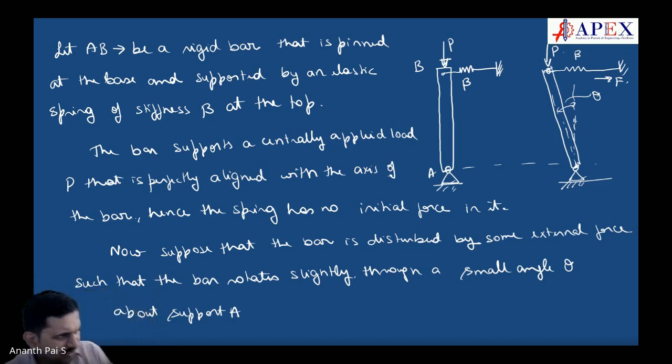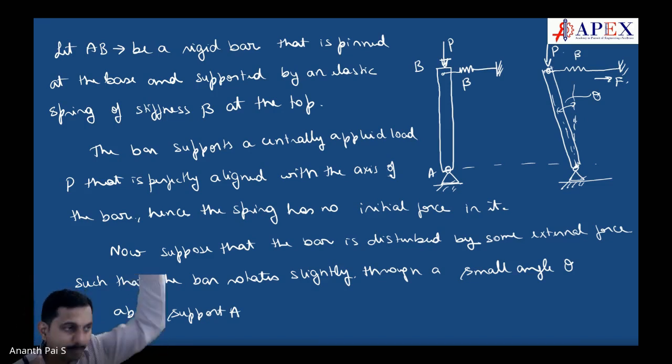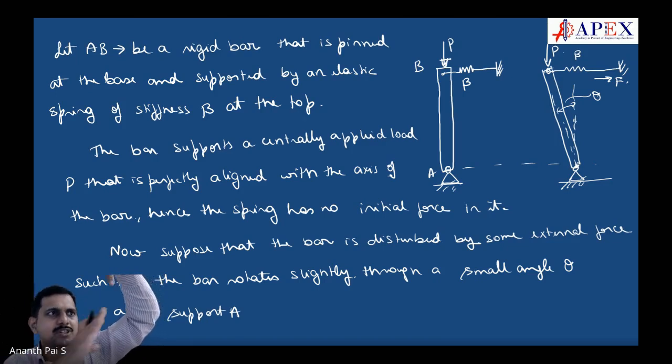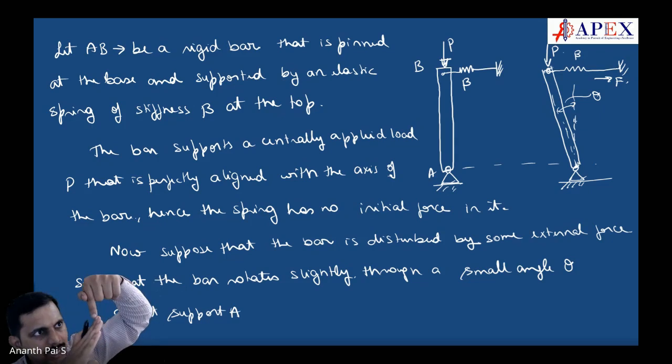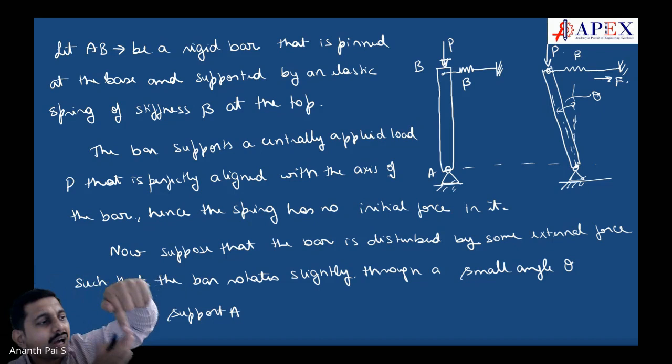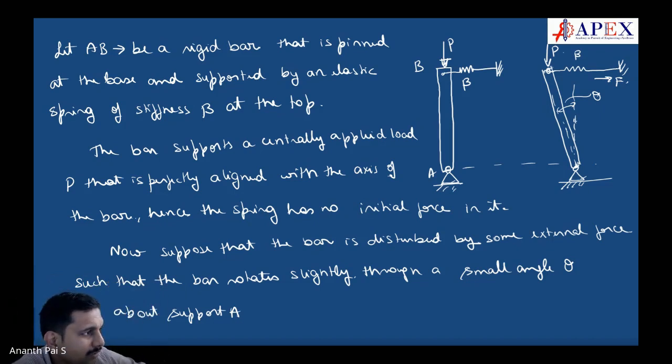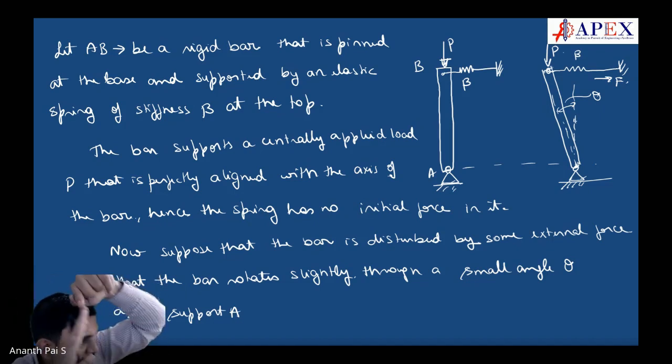Now, once it is disturbed, what controls whether it goes till the end with large deformation, or has small deformation? The load P decides whether it will have a bigger or smaller deflection. If a small P is acting, it will stay there, and when the disturbance is removed, it will come back. Whereas if you put a large force, it will go on increasing until it fails.